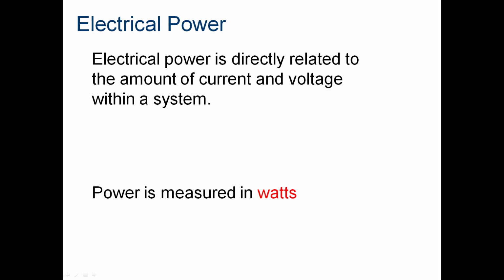So I need to be in a volt relationship and an amp relationship. If I'm in a milliamp relationship when I multiply it, I get milliwatts. If I'm in a kilowatt scenario, I either had kilovolts or kiloamps as the inputs there. So we have to pay attention to our factors of 10 as we multiply those out. That's it. P equals V times I, or I times V.